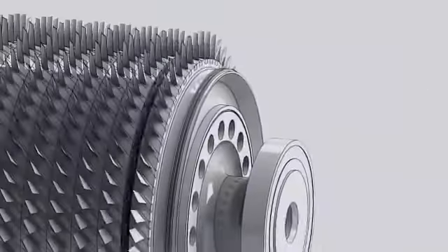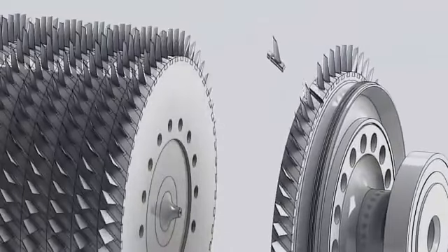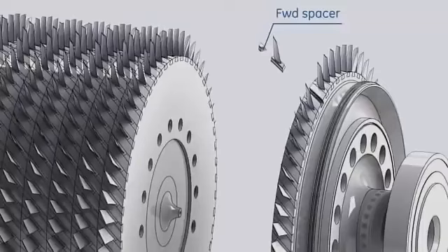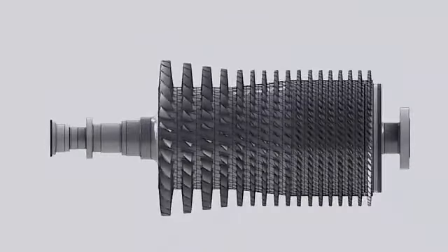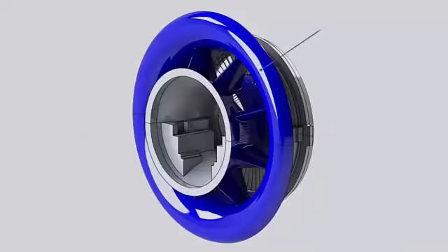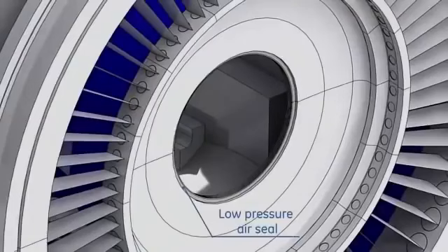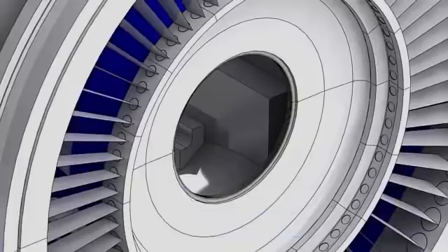The 17th stage blades are mounted on the wheel portion of the aft stub shaft, and they have only forward spacers. These spacers are placed to maintain the relative position between the rotor and the stator blades. Rotor blades are held in axial position by staking at both ends.